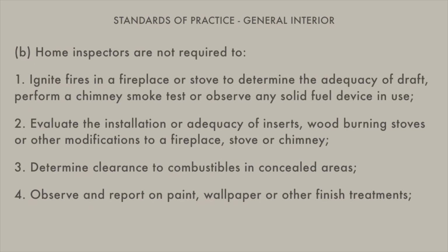Home inspectors are not required to ignite fires in a fireplace or stove to determine the adequacy of draft, perform a chimney smoke test, or observe any solid fuel device in use. Evaluate the installation or adequacy of inserts, wood-burning stoves, or other modifications to a fireplace, stove, or chimney. Determine clearance to combustibles in concealed areas, or observe and report on paint, wallpaper, or other finish treatments.